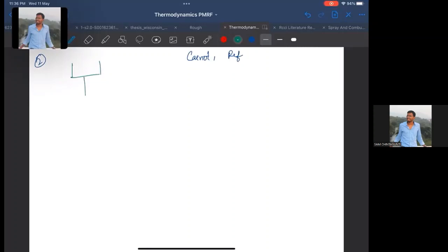Reservoirs of refrigerator works like this, and here it is minus 30 plus 273 Kelvin. Remember, all temperatures have to be in Kelvin. All right, and 44 plus 273 Kelvin. So the lower temperature becomes the TL and higher temperature becomes the TH. It need not be given that the higher temperature is this and that. So that has to be understood.